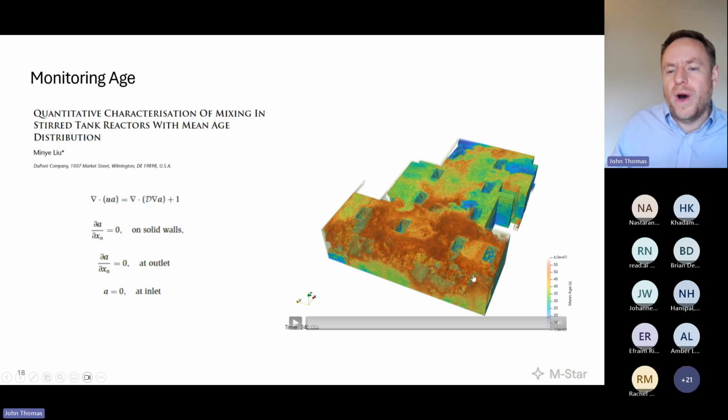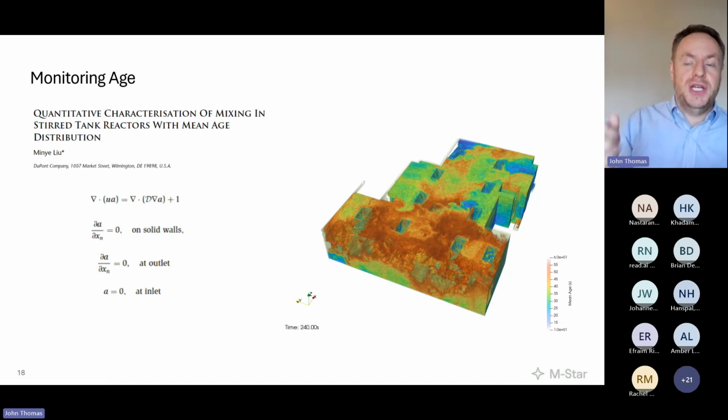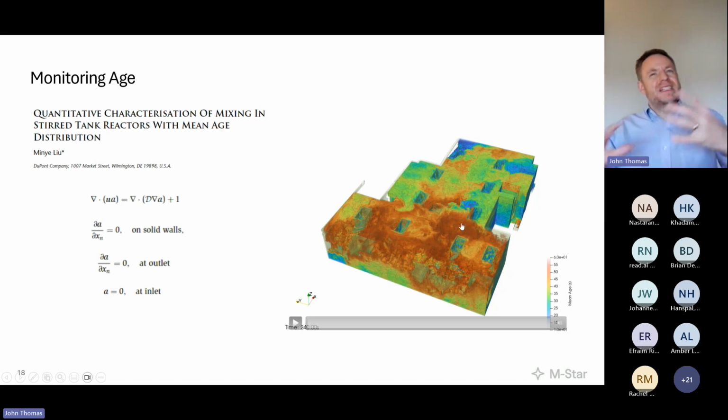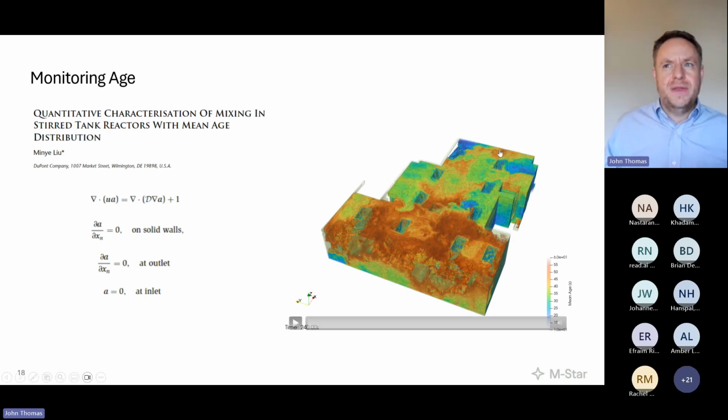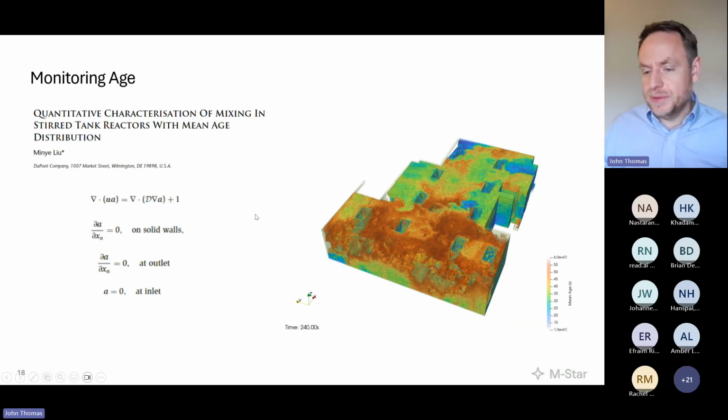I probably wouldn't want to keep product over here, where the air is, well, stagnant is not the right word, but the air is certainly vintage. Let's put it that way. The air is certainly matured. We're not getting the youngest, freshest molecules in the room anymore. But being able to see not just where the air goes, but how long air tends to spend and where the oldest air tends to sit and reside is useful for understanding where we don't want to put our stuff if we're trying to prevent it from being in a region where air has had a bit of time to, crust, for lack of a better word.